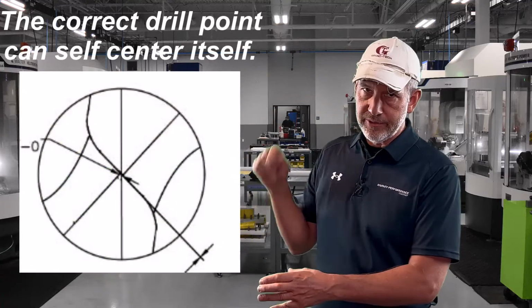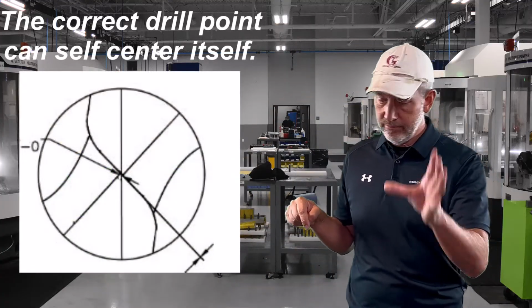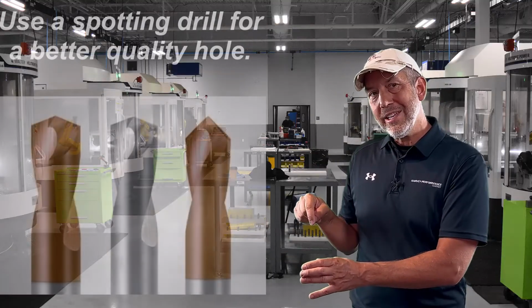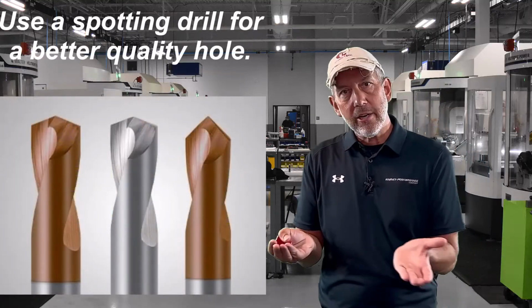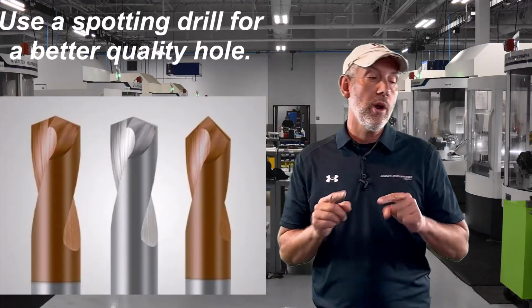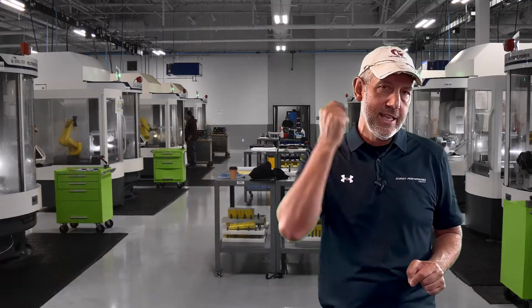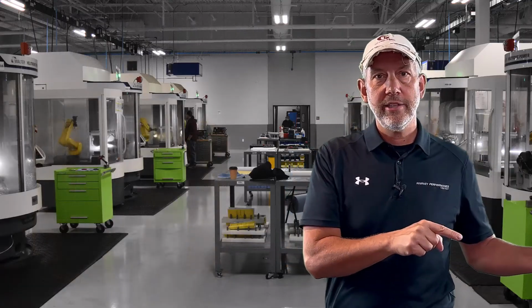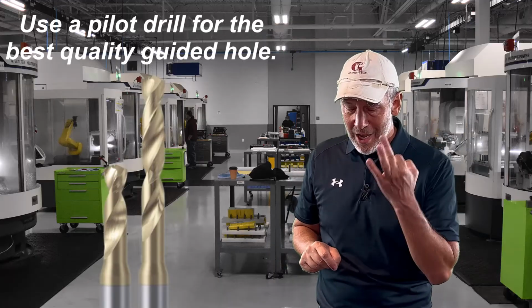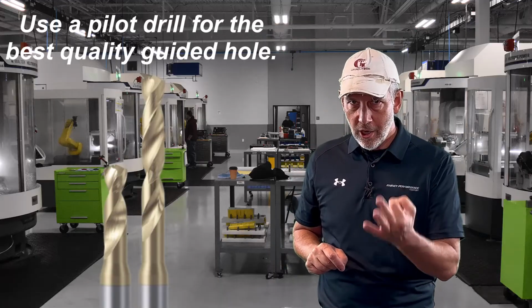Number 1, like we said, a point is designed to self-center itself. If you want a better quality hole, get a spotting drill. A spotting drill is going to be flatter than the angle you're doing, drives the point, and gets it going in. If you really want that pristine quality hole, put a pilot in there. A pilot's going to guide your drill straight through the hole, and you're going to get great primo quality of that